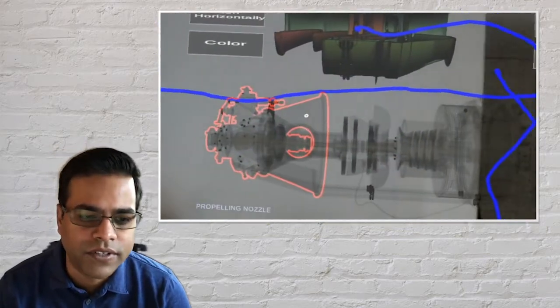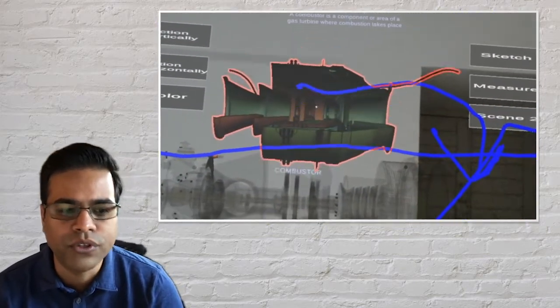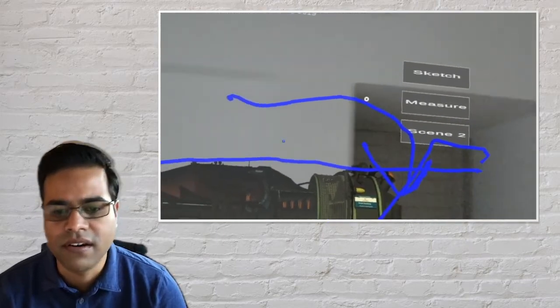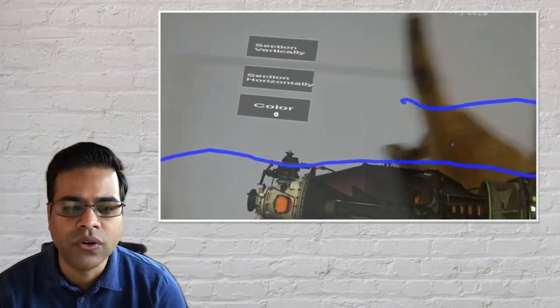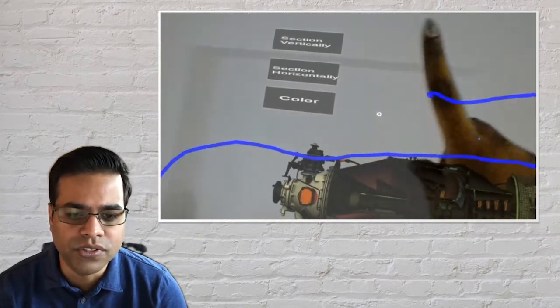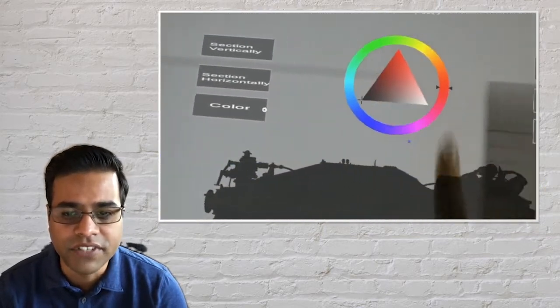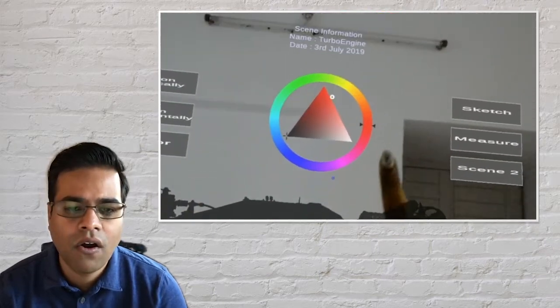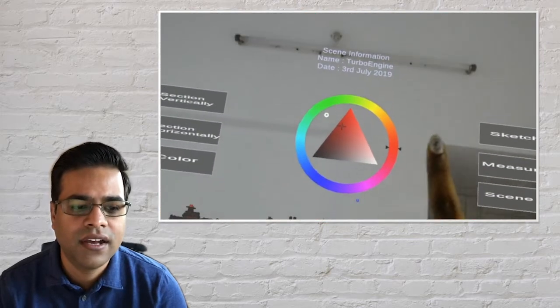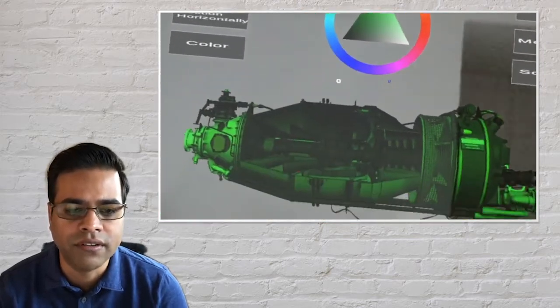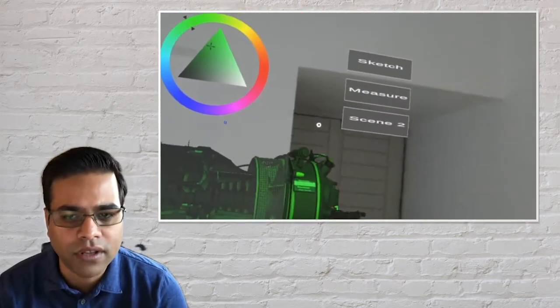So they now have to decimate the model to bring it down to a few thousand, maybe 100,000 polygons that these devices can accommodate. And in doing so, you basically either lose significant feature details of the CAD model, or you have to manually start adding and subtracting parts that you require to visualize. So you're basically making the model smaller and smaller.